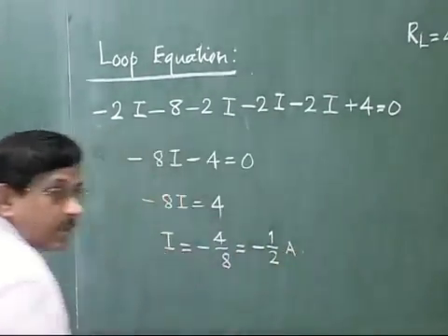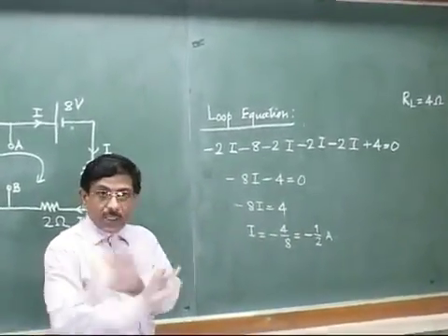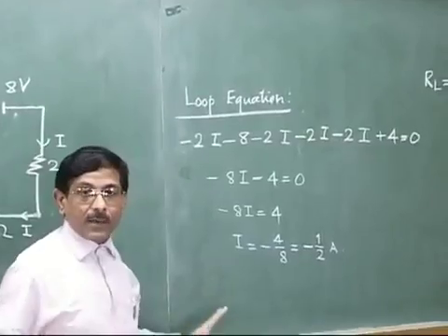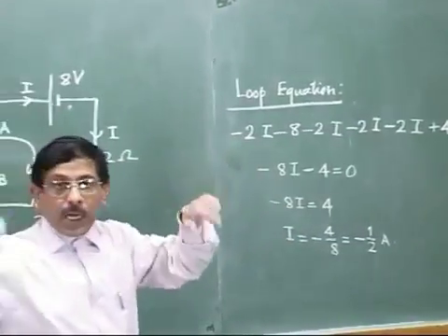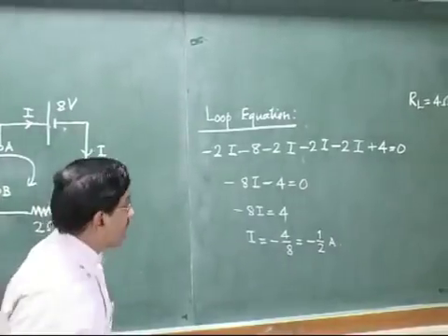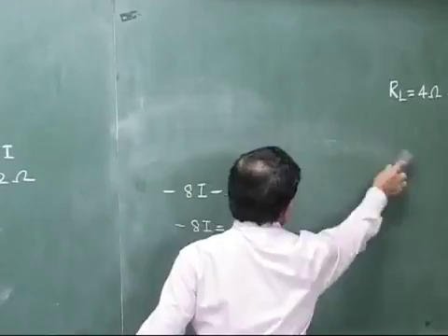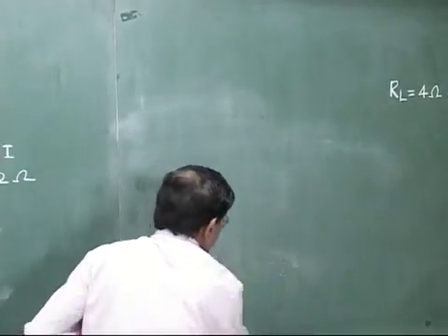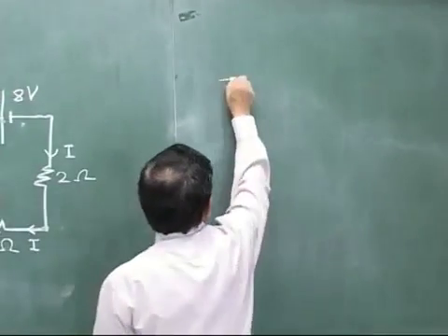Now here we have got a minus answer, let it be minus. We have not to change any signs anywhere in this procedure. So second step we have implemented. Now see step 3. What is this step 3? In step 3 we have to find out the value of VTH. So step 3 will be to find VTH.